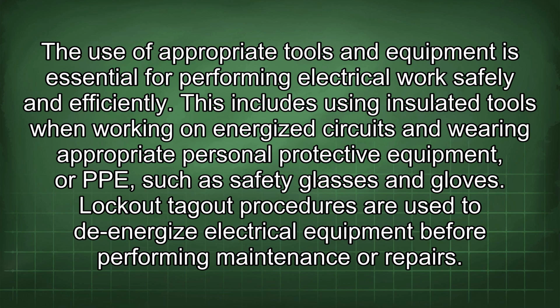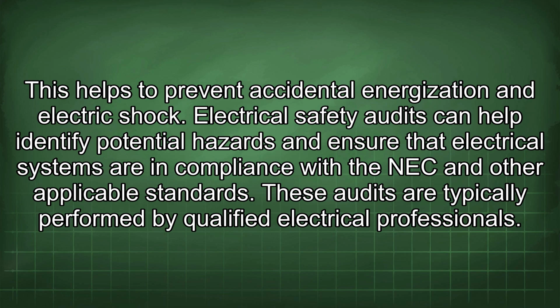This includes using insulated tools when working on energized circuits and wearing appropriate personal protective equipment, or PPE, such as safety glasses and gloves. Lockout-tagout procedures are used to de-energize electrical equipment before performing maintenance or repairs. This helps to prevent accidental energization and electric shock.